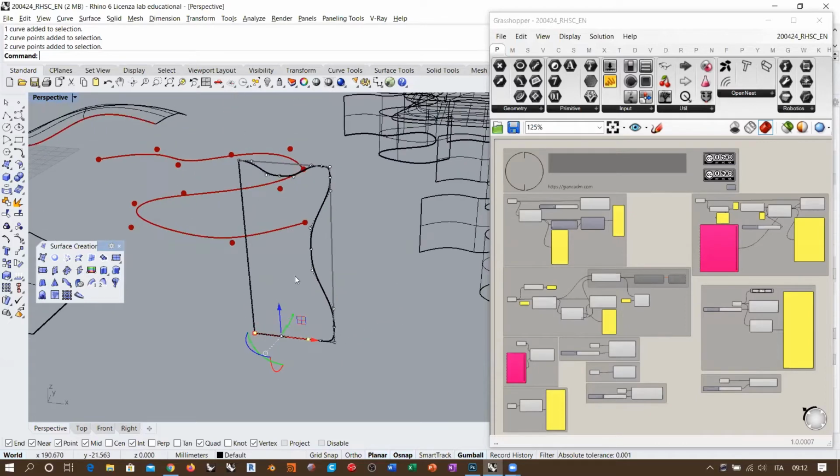And this is important because as this profile is going to revolve around this axis, if I don't have a horizontal tangency, or rather a tangent which is perpendicular to this side, then during the revolve I will get some vertex or discontinuity in these two endpoints.